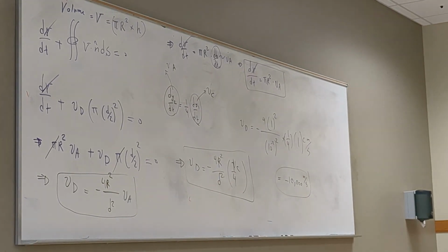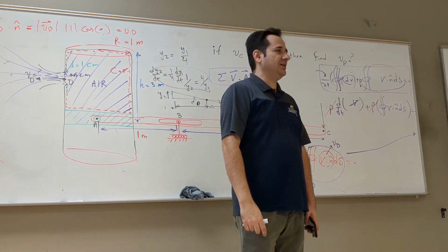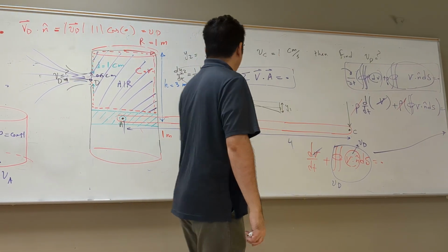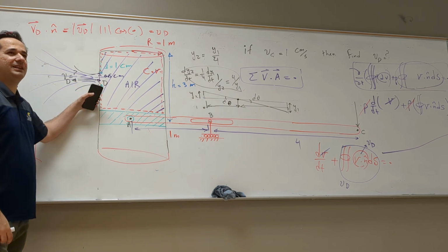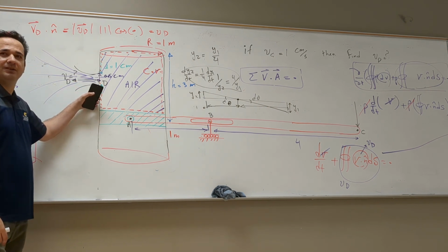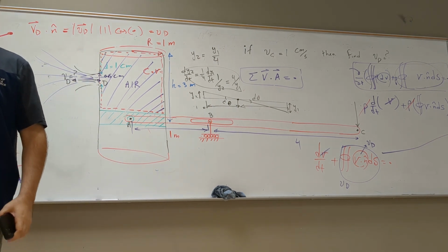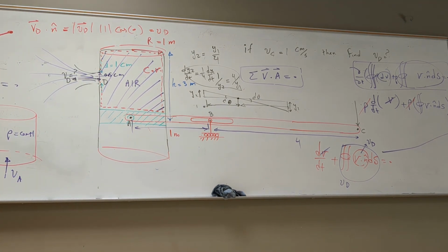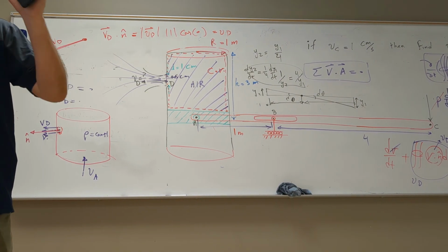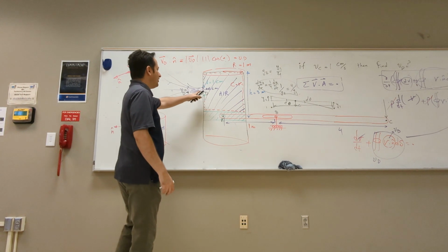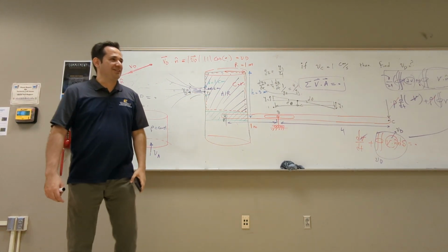It may or may not, depending on how you design this nozzle. If this nozzle is not designed very well, later on in compressible flow, you see that you get a shock wave here, and this shock wave will break the speed. It causes extra delta P, the pressure drop, and you never reach the velocity. Assuming the nozzle is perfectly done, there is no shock, yes, it can reach the velocity, but it's crazy.